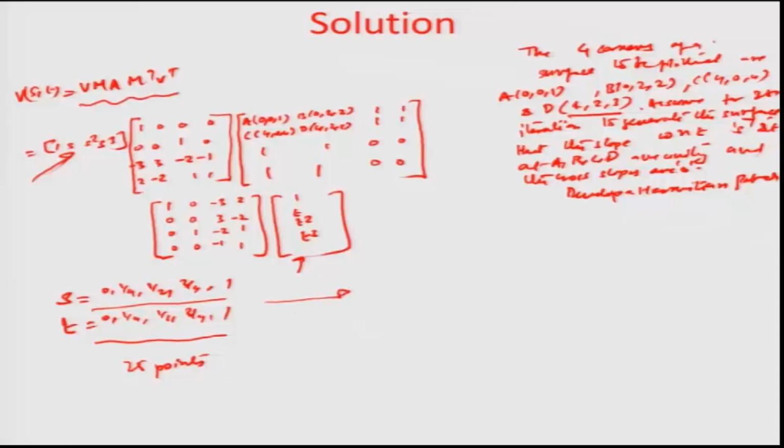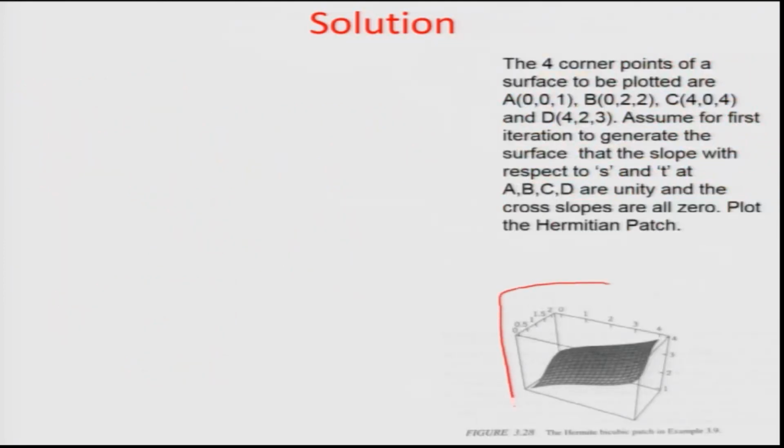I am not going to actually show you how I did these MATLAB oriented computations, but if I wanted to look at how the plot of the surface would look, it typically looks something like this, okay. Here probably we took a little more than just 5 different points. You could take points in steps of, let us say, 0.1 or 0.2 to resolve the surface very well. And so, you can see a 3-dimensional surface patch getting generated, which has variation along 2 independent variables in the s and the t direction, and a certain value of z based on the s and the t values at a certain point.